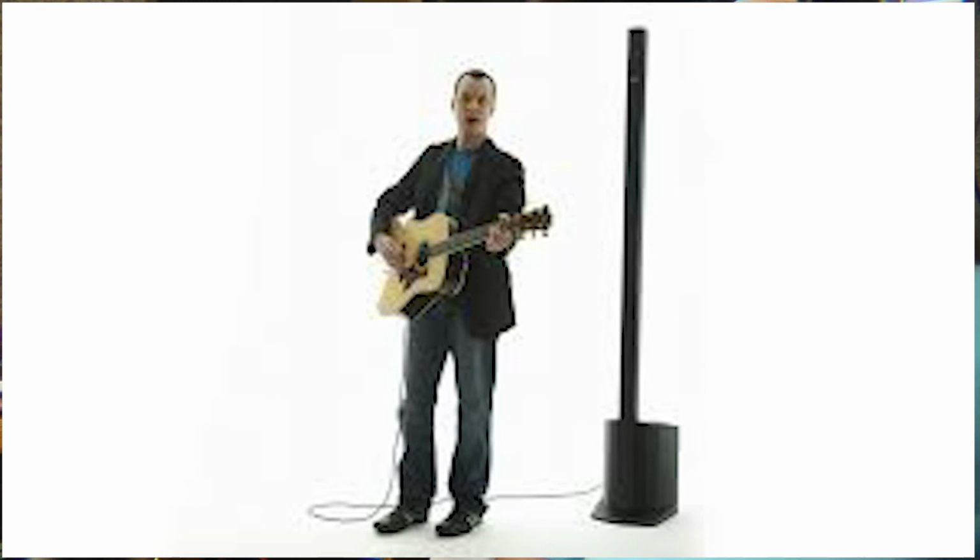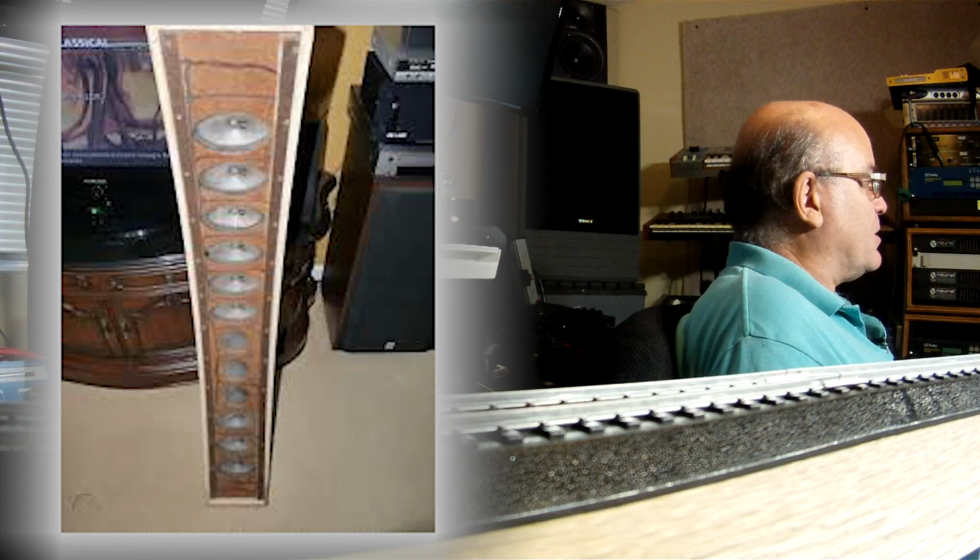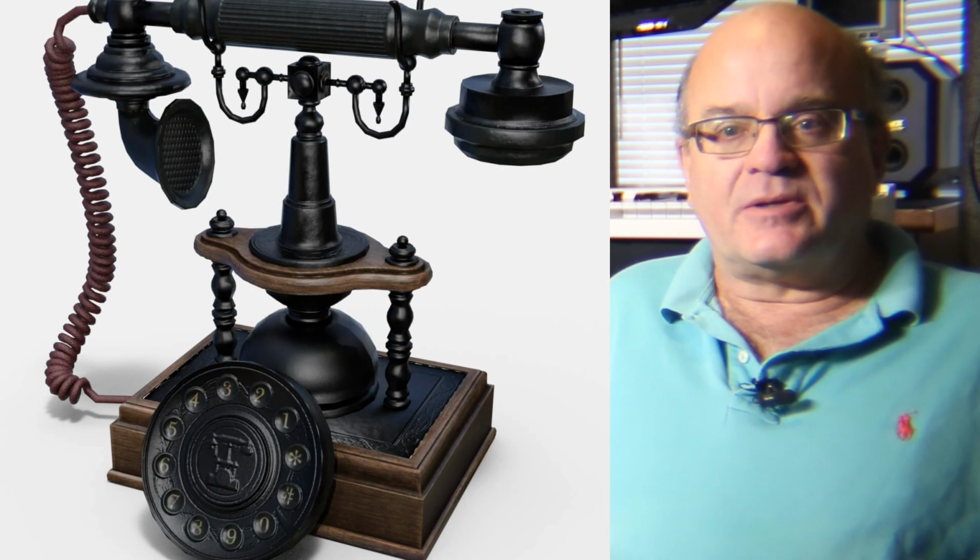This can be handy for a single guy playing a guitar in the back of the lounge so he can use the PA speaker as his monitor, but lousy for trying to do speeches and other information inside of a conference or a convention. For the most part, as you can see in this illustration, they're made from a whole bunch of 3 or 4 inch speakers mounted inside of a long column or a long tube. This also means that absent a lot of processing, most of them sound fairly similar to a large telephone.